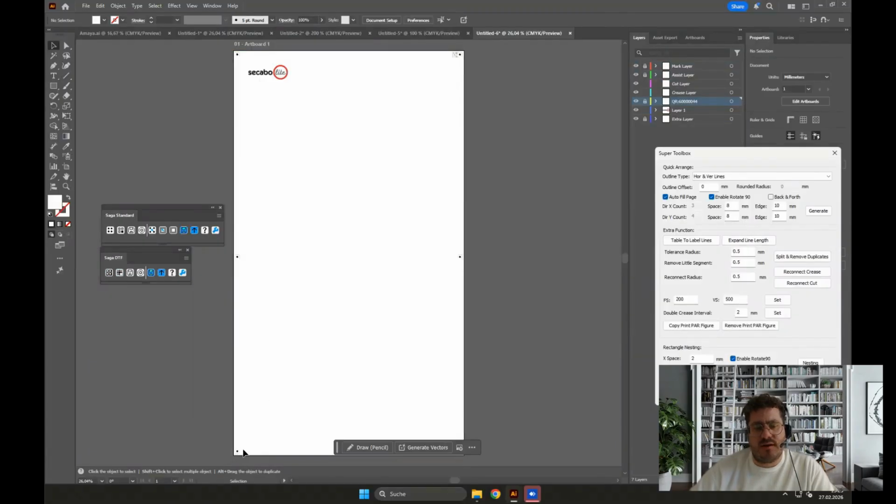As you can clearly see, intermediate registration alignment reference marks are also being generated along the outer edge. This is given as a small reminder, because the work table of the DTF Multicut system can only accommodate a maximum total length of just a little over 800 millimeters in a single setup or one continuous run. Everything that exceeds that limit must be set off with visible interim markers.